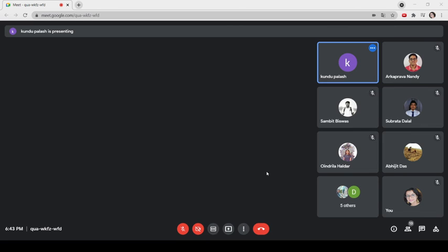And C/T will be 1. That means the timer will be operated as a counter. So upon occurrence of each signal, there will be a measure of the event count, which is stored in the timer data register. So if we set the timer data register initially to 0, then running the timer as a counter, we get a direct measure of the occurrence of the number of pulses, which is called event counting.